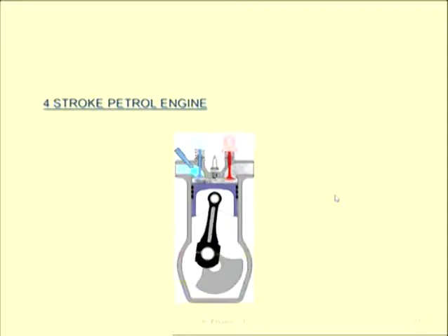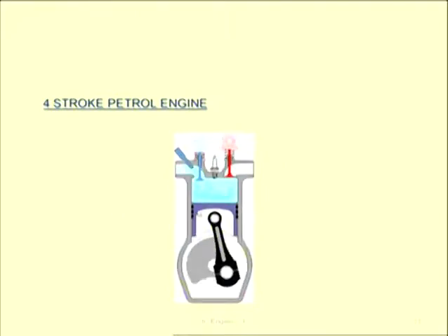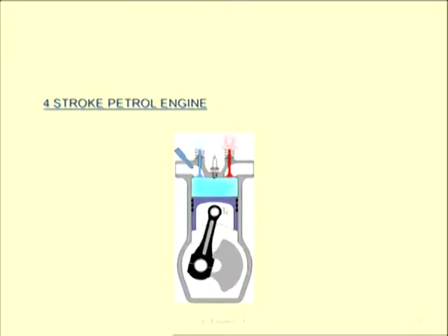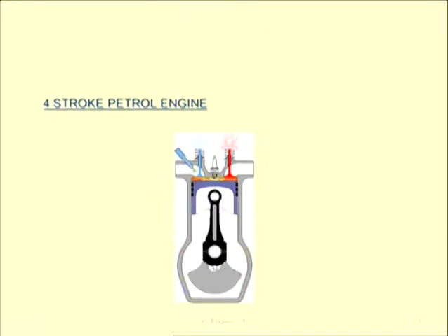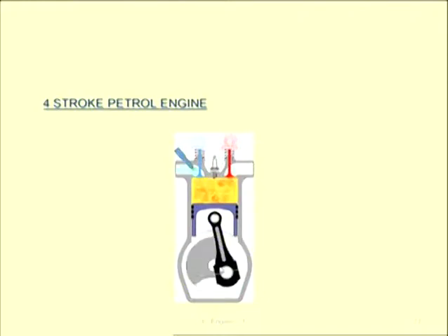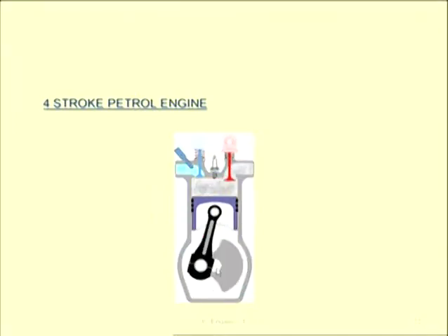Now as I said that in IC engine the reciprocating motion is converted into a rotary motion. How? You can see in this particular animation. The reciprocating part here is nothing but piston only. It is connected with the connecting rod, and then it is a crank. So this mechanism, when it is moving up, the white color shaft you can see. So all motion, reciprocating motion is finally converted into a rotary motion of shaft. Because if you use your IC engine for automobile purpose, your requirement is to rotate the wheel. So the rotating speed you are getting by conversion of reciprocating speed into rotary motion.